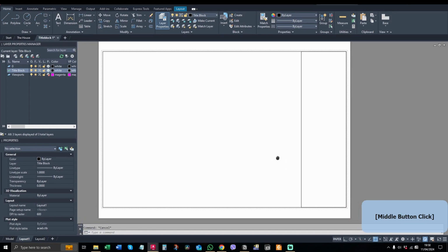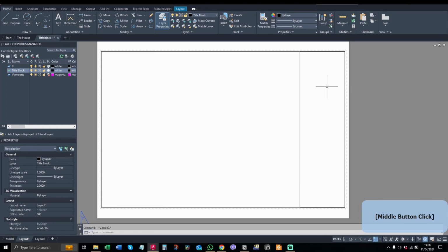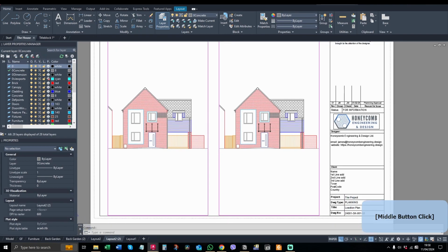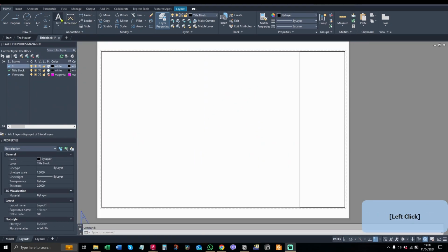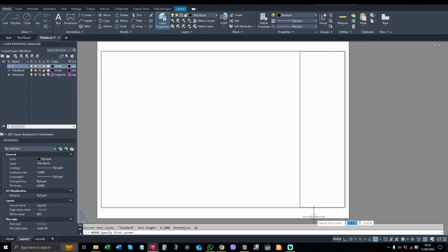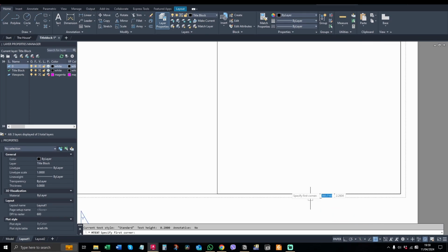And now we're going to put some lines in, and fill out all the boxes so that it looks like this. This is what we're going to make. The next thing I'm going to add is text. So I'm going to put some labels in. The title block, all this frame, and all the gubbins in here are going to be part of a block eventually. The bits we need to change will be attributes. I'll come on to that in a minute.